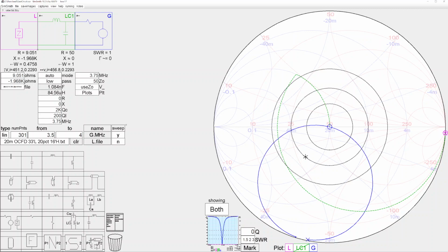So this is only a 33-foot long off-center fed, remember. It's not a 64-foot off-center fed. If it were, it would be able to handle 80 meters a little bit easier, maybe down at around 20 or 30 or 40 microhenries, which commercial professional tuners can handle. Just realize, by the way, that the little AT100 by N7DDC, maximum inductance of that guy is about 8 microhenries. So that's what you're limited to. So now you're seeing that you can find the limit of your tuner for any given band using SimSmith. Okay, so with that, let's move on to our next example.